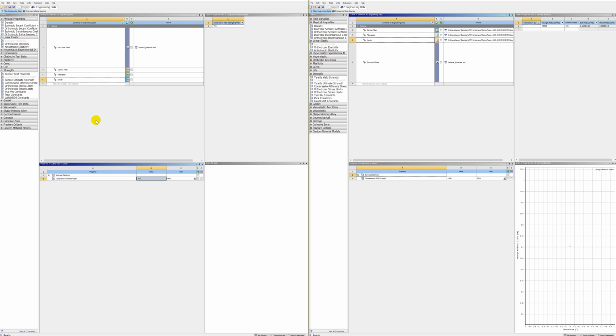Okay, a good rule of thumb is to add the properties relevant to what you'll be testing in your simulation. For example, if you have a thermal condition, you'll want a coefficient of thermal expansion data for all your other properties at different temperatures. At the very least, for static structural simulations, you'll want to specify Young's modulus and Poisson's ratio. If you don't know what those are by now, you can look them up on Wikipedia.